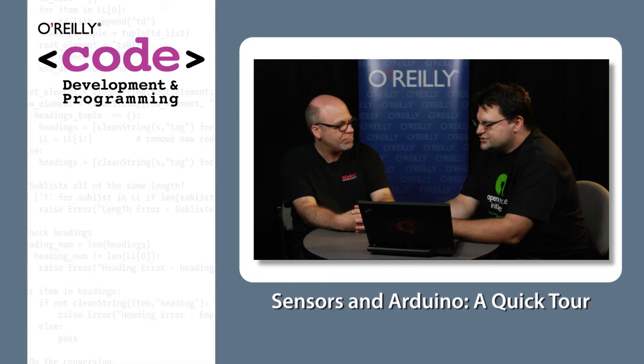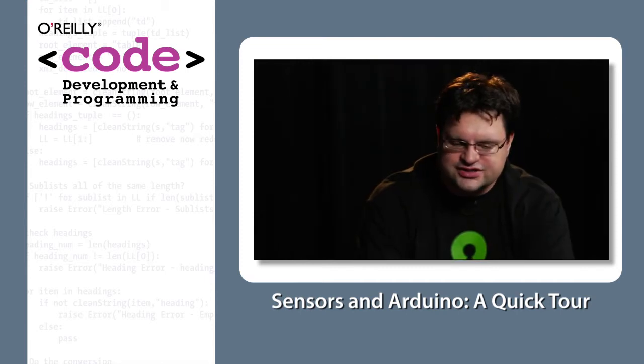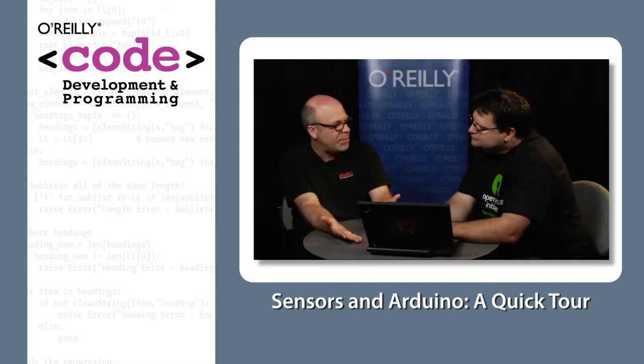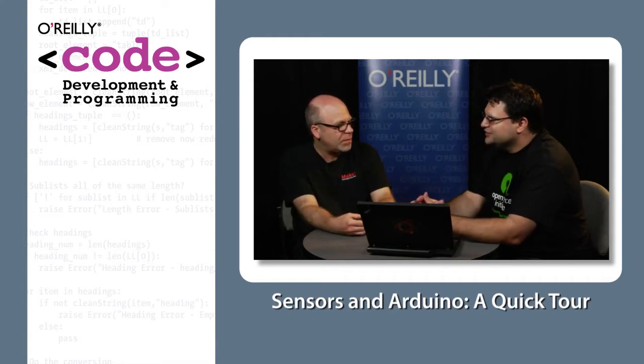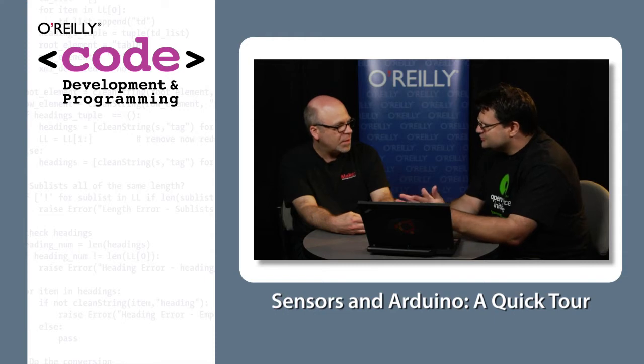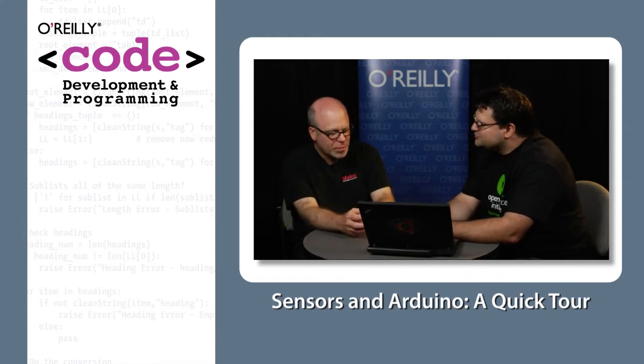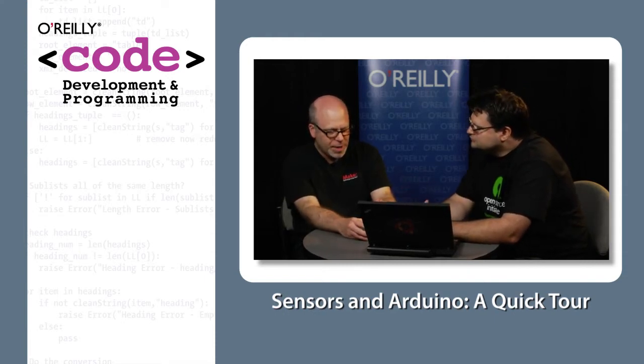For most sensors, I find that it's really very, very simple. Some of them are just dead simple, right? That's right. Because you're just reading either a pulse train or just a voltage, building a voltage bridge as you were describing before. When you're reading a voltage, it could be 0 to 5 volts. And the cool thing about certain microcontrollers, especially Arduino, is that they have a reference. They know what 5 volts is, and they know what 0 volts is.